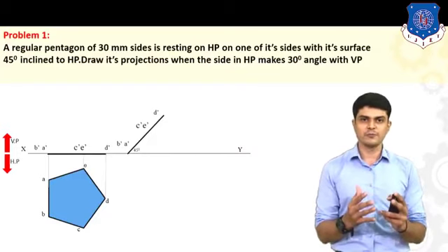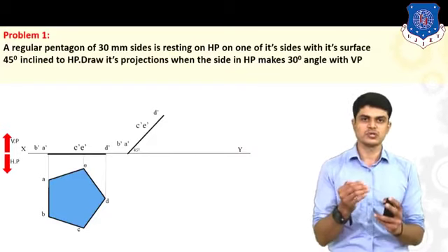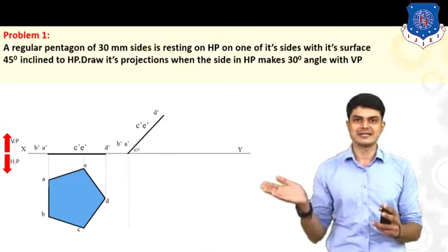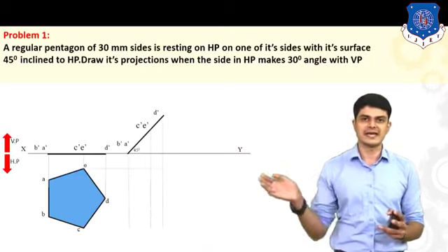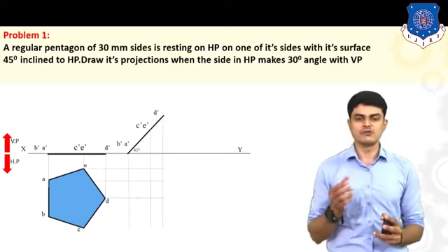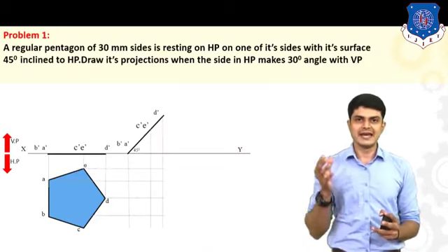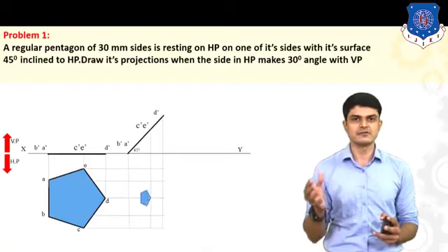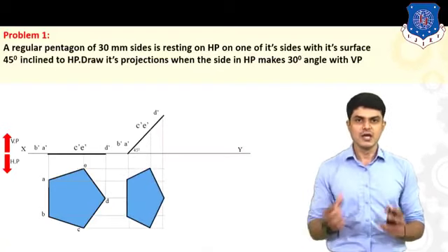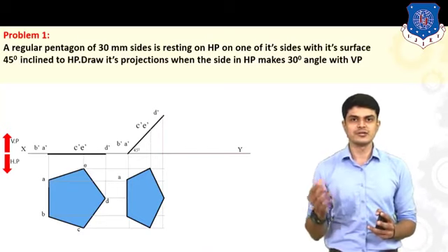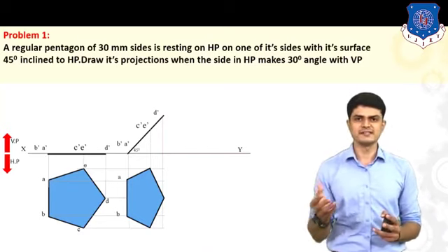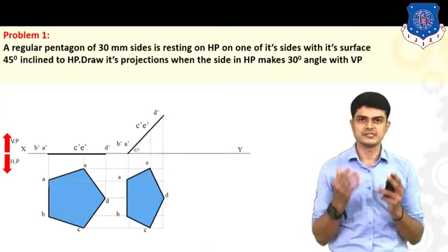After getting all of the points on your inclined line, you must draw the vertical lines from each and every point like this, and horizontal lines from every point of the pentagon like this on the right hand side. So you will have points of intersection, and after connecting these points of intersection you will have this shape generated, which is nothing but your pentagon. Let us give the notations A, B, C, D, E. It is in the same fashion as given in your first stage drawing.